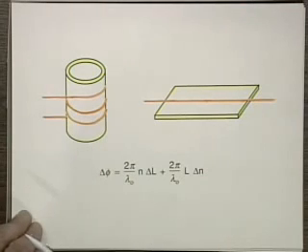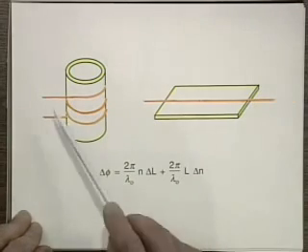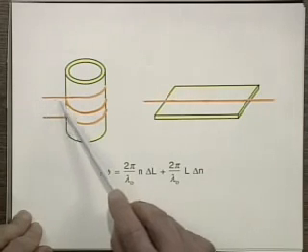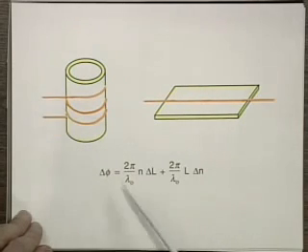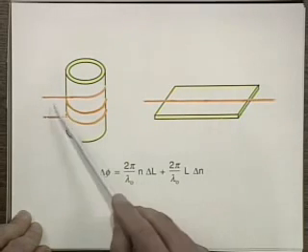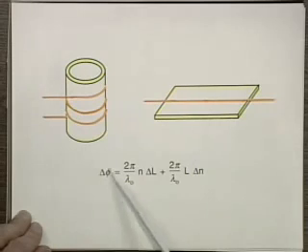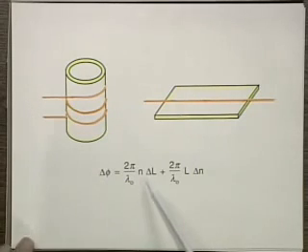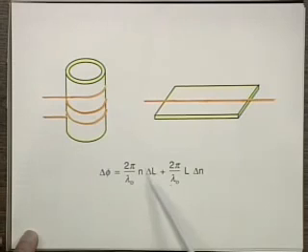All right. And now I wanted to say again a few words about phase modulators. Now, phase modulators, how do you do that? How do you modulate the phase of the light propagating in the fiber? Well, again, there are many ways, because if we stretch the fiber, or do something to the fiber, we can change essentially the index in the fiber, or change the physical length of the fiber, and then we get a change in phase, delta phi, that's proportional to either the change in the length of the fiber or the change in the index of the fiber.